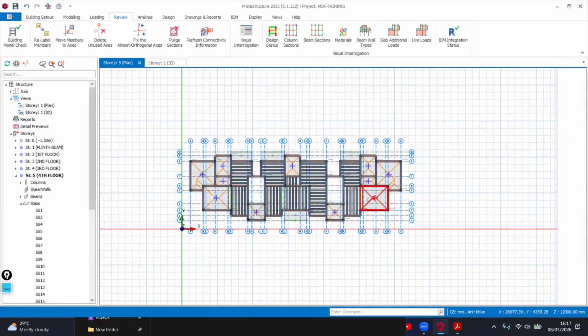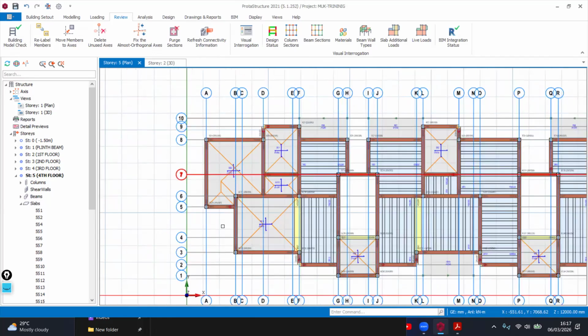That reason is, we have 2 types of slabs. We have one-way spanning slabs and 2-way spanning slabs. For 2-way spanning slabs, the load transfer is in 2 formats. We have triangular and then trapezoidal transfer. Okay, let me explain it this way.